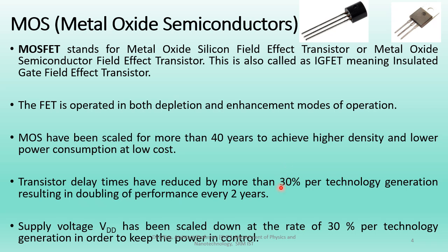Whenever a new technology generation comes, the delay gets reduced by 30% and performance doubles every 2 years, which is Moore's law. The supply voltage VDD has been scaled down to manage the power inside the device.